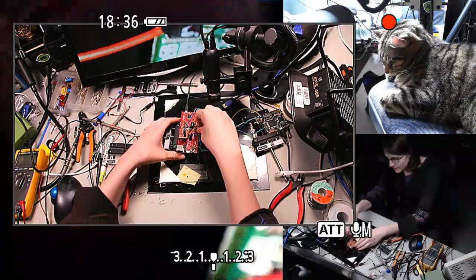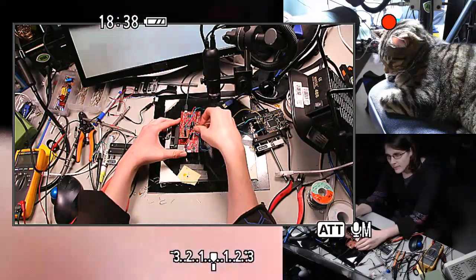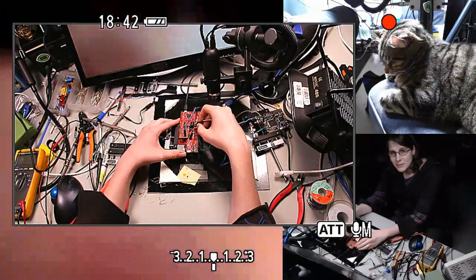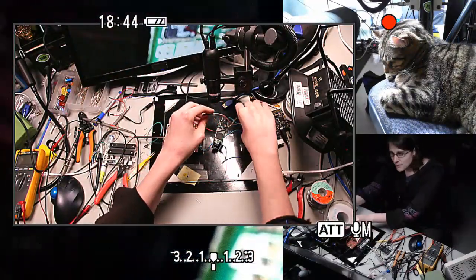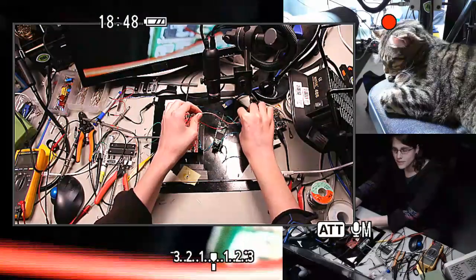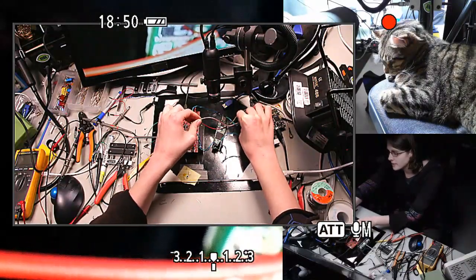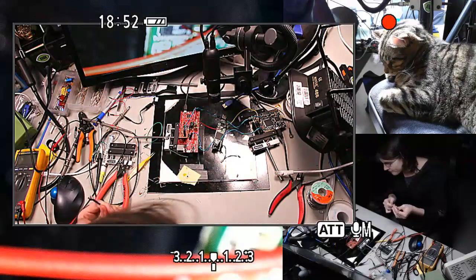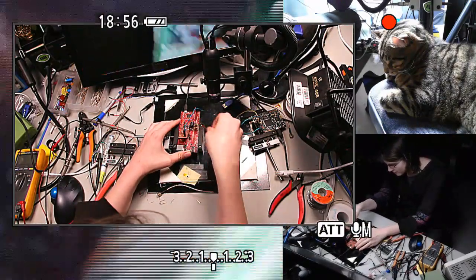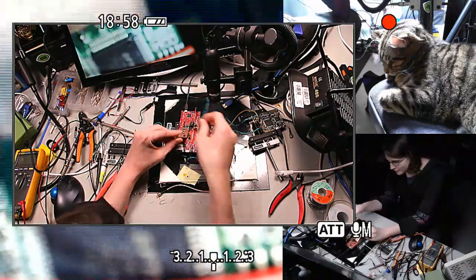Last time I worked with it, there were major features, like it was supposed to have TCP/IP checksum offloading, but due to some bugs in the chip it's unusably broken, so you just can't trust it. You have to do it in software, stuff like that. Some of the chip features have bugs where you have to occasionally retry.